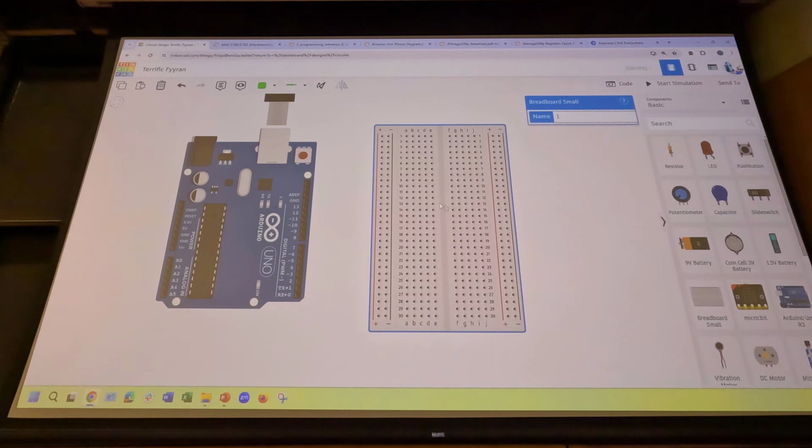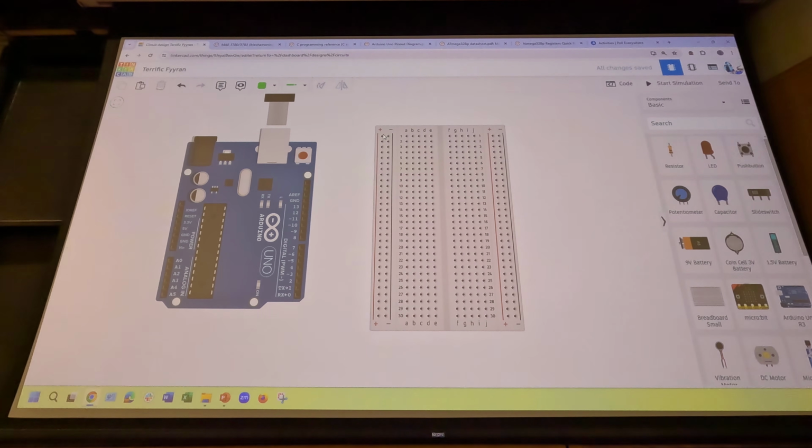Kind of first general step here, connect your power buses. Don't just do this. I can't tell you how many times I taught this class last time and I would walk around and see students just with a bunch of straight green wires crisscrossing everywhere. Okay, so use color coding and make them neat so it is easier to trace and debug them later.